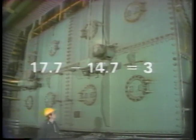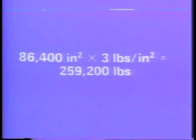But when you consider the force acting on the water box, the purpose of this heavy construction becomes clear. We can find the force by multiplying the pressure difference across the water box by its area. A typical water box might have about 86,400 square inches of surface area. When we multiply this times the 3 psi difference in pressure, we get a total force of about 259,200 pounds acting on the water box. It must be constructed to withstand this great amount of force.